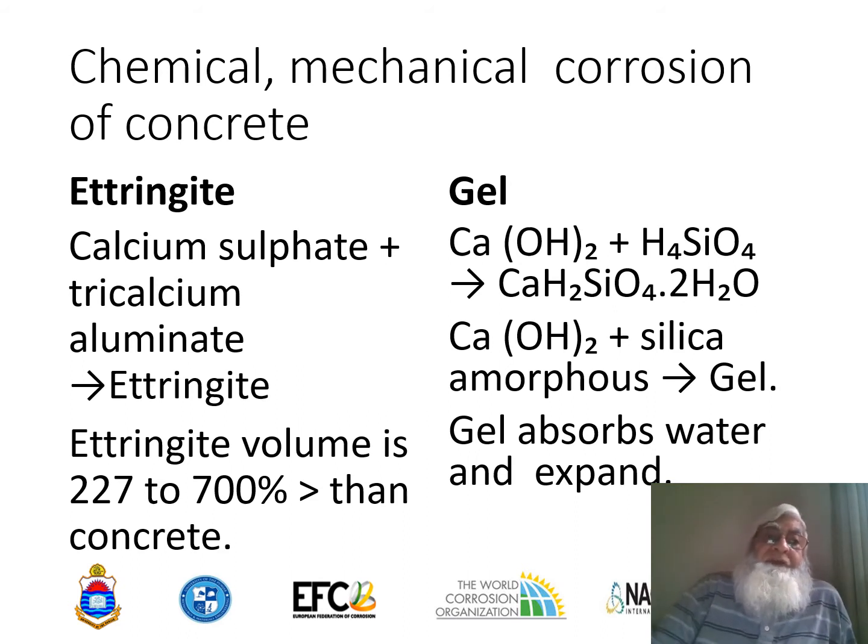Another possibility of this chemical reaction is that the calcium hydroxide of the concrete reacts with silicic acid, which comes from different sources, forming calcium hydrosilicate and water. And then calcium hydroxide also reacts with silica, which is amorphous in nature, forming a gel. Now the gel in there starts absorbing more water, and it keeps on expanding and putting a mechanical pressure on the adjacent concrete, and the concrete disintegrates, developing cracks.